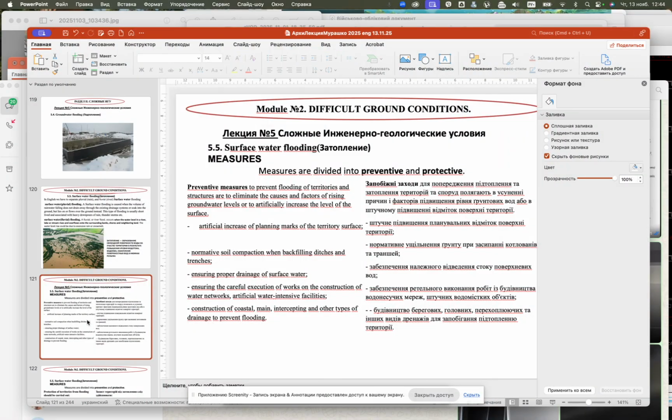So add additional sand layers or gravel layers, layers which can place your building as high as possible above the future surface water flooding. Also, compaction of the soils can increase the protection of your building from surface water flooding.